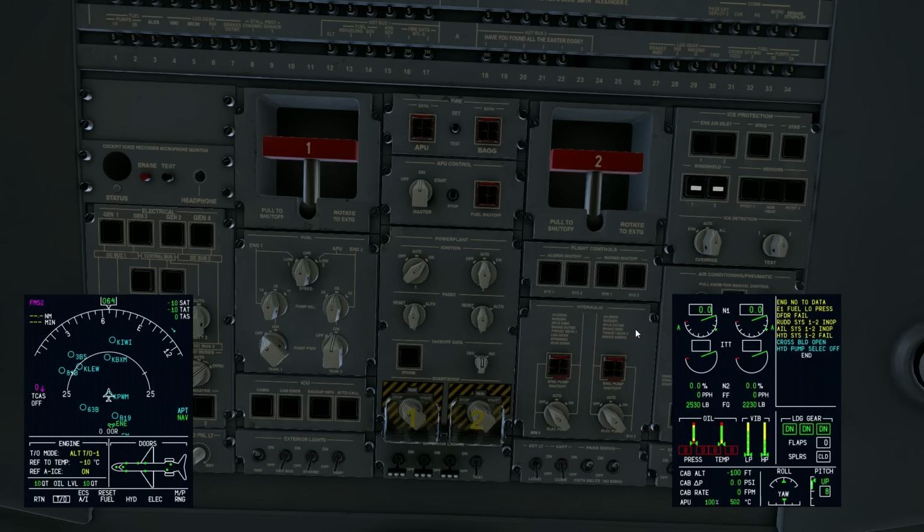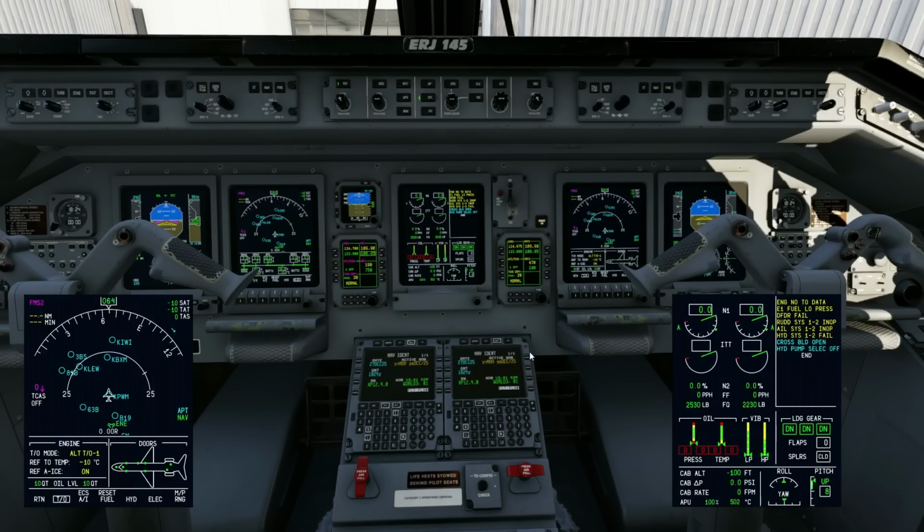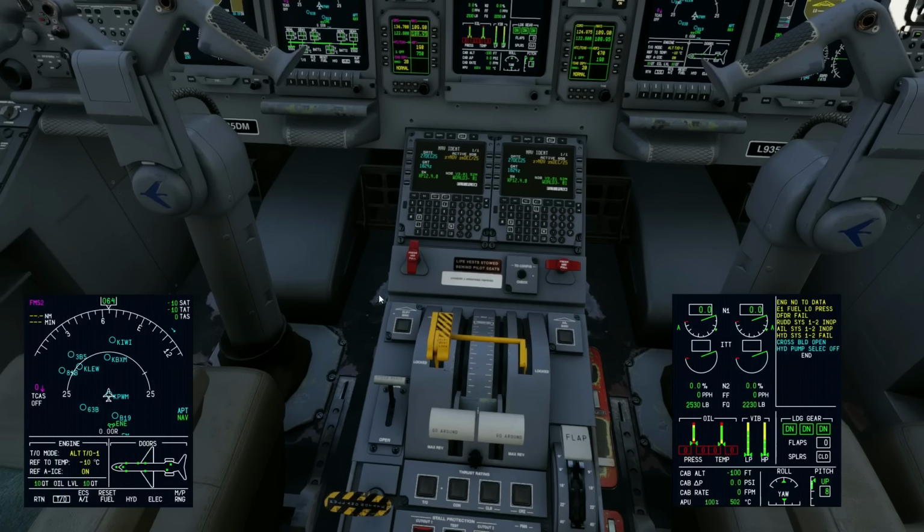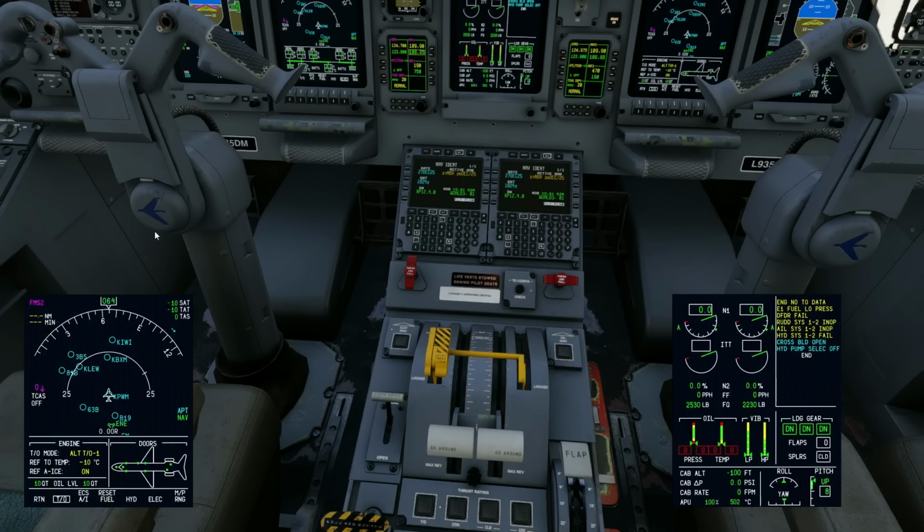So, hydraulics on this aircraft: the way the flight controls work is our ailerons and rudder are hydraulically boosted, and our elevator is completely manual. The elevator is directly connected, with control cables running directly from your yoke to your elevator, which is part of the reason why we have a gust lock. We have a gust lock because, again, what works one way works the other. If it's a windy day and your gust lock is inoperative, you have to spend your whole time holding the yoke because it's going to try to move around.